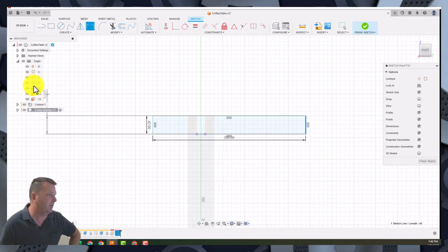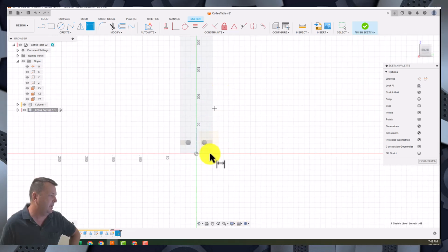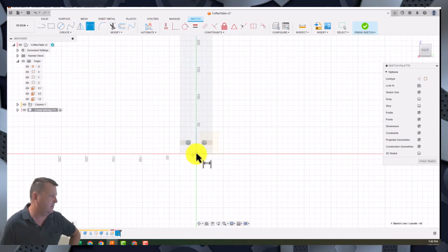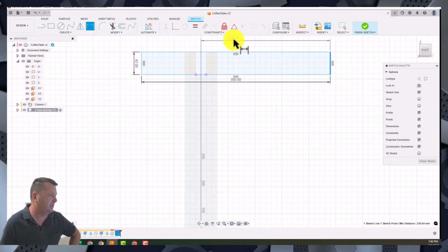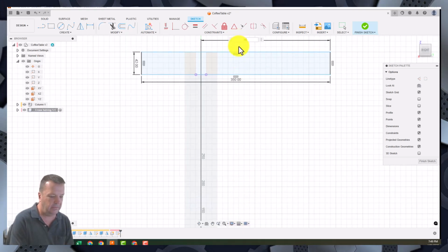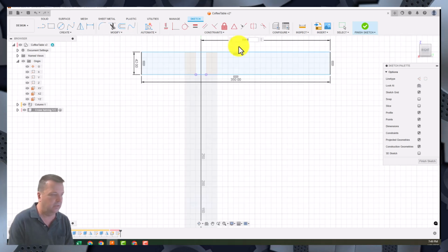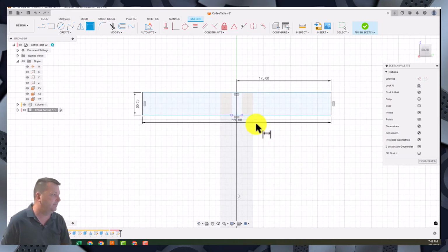Let's try a look. We're looking for the Z-axis. I don't think we can. Okay, so you go down, pick our origin point, that little dot down the bottom there is our origin point, and bring your mouse back up and click, and we want 350 divided by 2 is 175, and there we go.